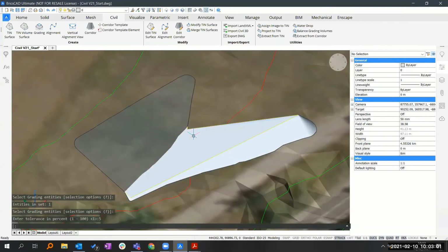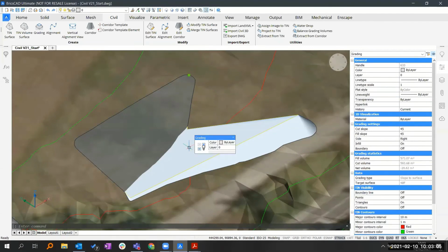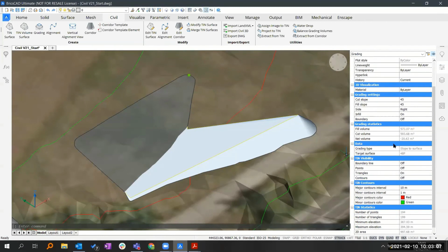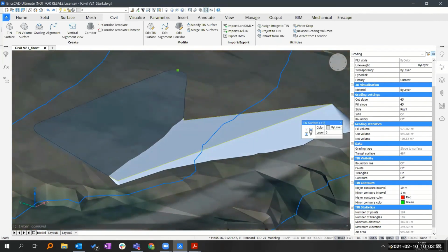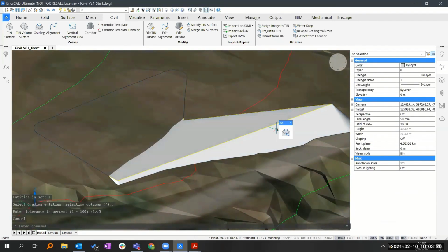You will see now it's replaced the elevation of my grading because it was searching for a number that is as close to the net volume 0 as possible in order to have the fill and cut as close as possible to be cost efficient basically. So in that case, my grading should be somewhere like this in order to have a net volume close to 0.